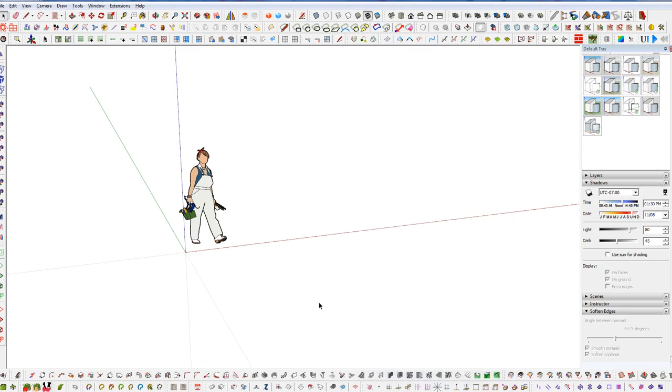And what Flowify is, it's very similar to, if you're familiar with Shapebender. What Shapebender does is it takes some reference line and allows you to bend a piece of geometry based on the principles of that line, that reference that you're using. Now, Flowify does a very similar thing.